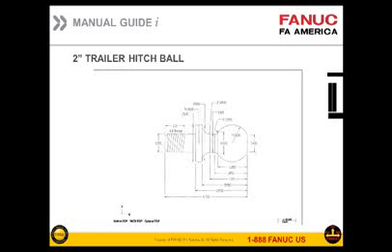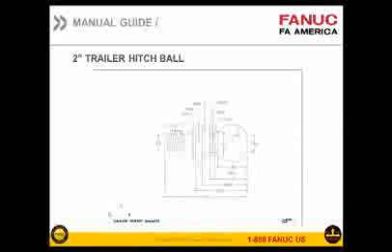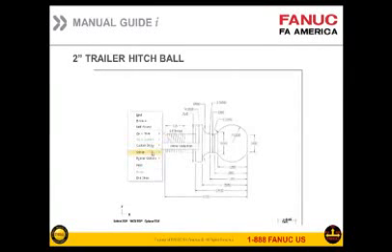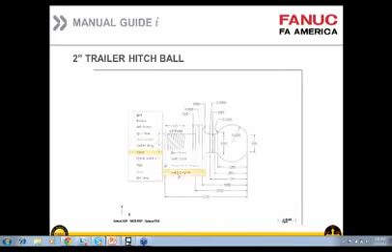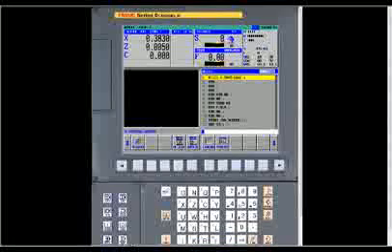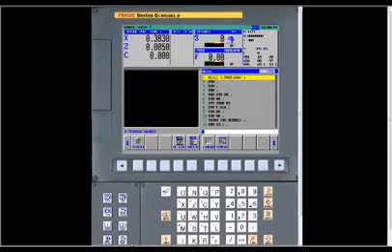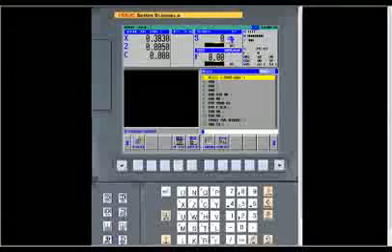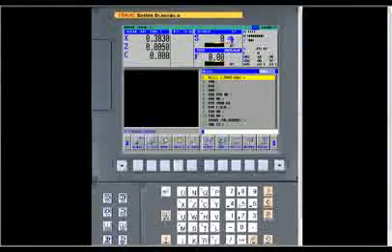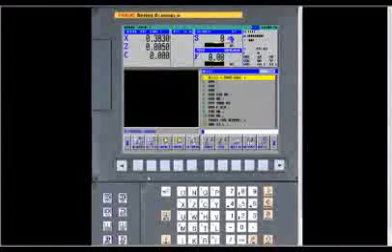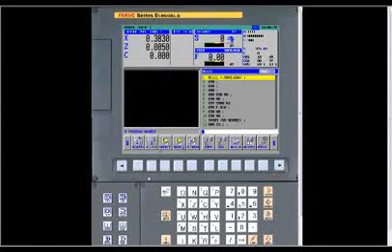And again, what we're going to do today is like what we did a few weeks ago when we did the setup. We're going to use NC Guide and actually use the interactive Manual Guide Eye to actually do the programming. So at this point, I'm going to change my screen, switch programs, and we actually go into the NC Guide. And now to start a new program, you always want to go into the edit mode. And when we go into edit and go left shift, this will typically be the screen when you first go into the edit mode.